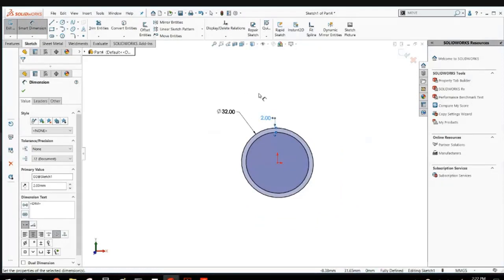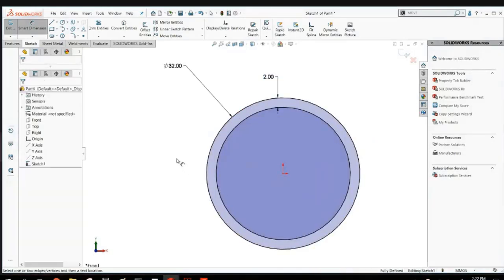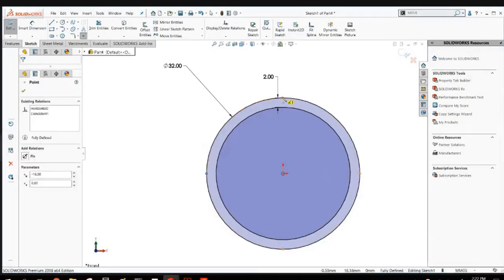When you are placing your cross section, you'll always pick whatever this origin was in your sketch for the line that it's going to draw it along. If you want to give people the ability to select the edges of this to run the pipe down, you need to put a point in there.